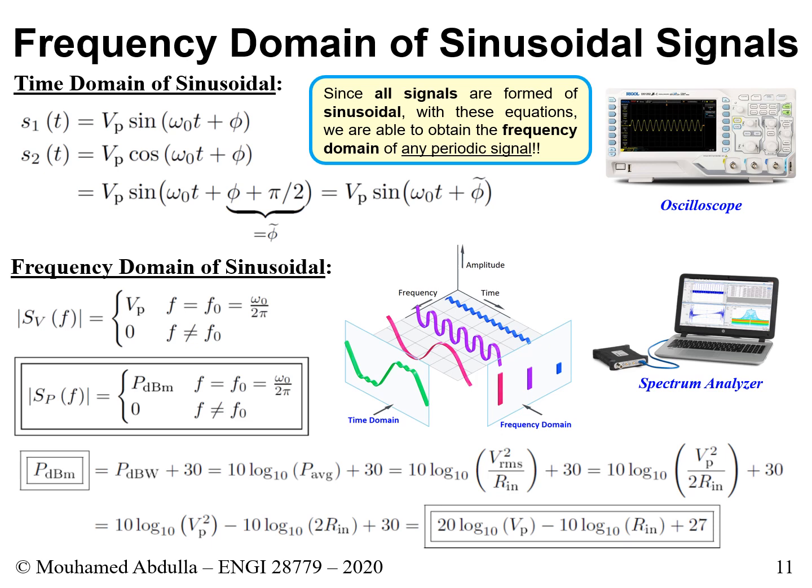Here you're multiplying, so you could simply break the 2 apart. You could have one component as 10 log 10 of 2 minus 10 log 10 of Rn, and 10 log 10 of 2 is equal to 3, but there's a minus in front of it, so it's minus 3. So 30 minus 3 becomes 27, and this is what you get.